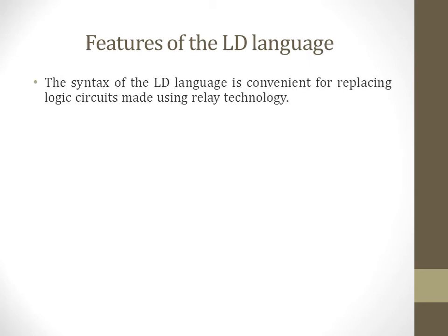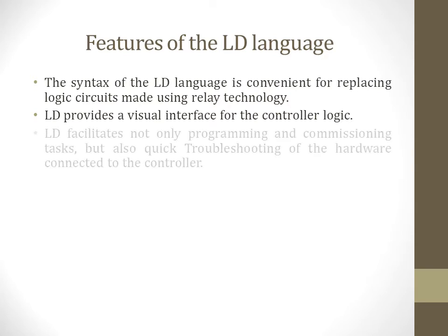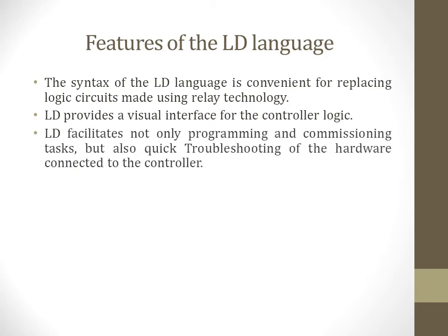The syntax of the LD language is convenient for replacing logic circuits made using relay technology. LD provides a visual interface for the controller logic. LD facilitates not only programming and commissioning tasks, but also quick troubleshooting of the hardware connected to the controller.